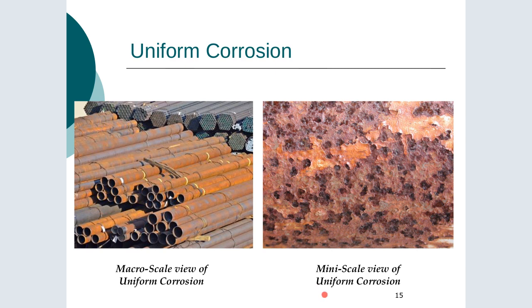Use these slides and this lecture as a starting point, just to get you running on it. We can see here some examples of uniform corrosion on some piping, and it doesn't look great, but it's not a concern. We build in corrosion tolerances into pipes for uniform corrosion, so we know that we have our thickness, which we will do according to standards.